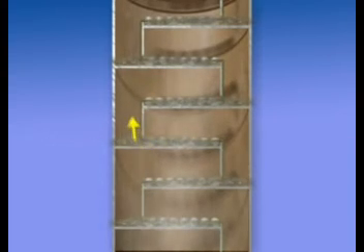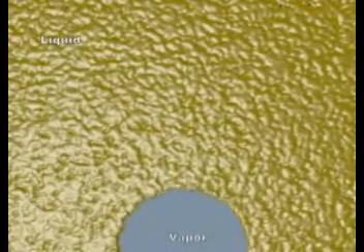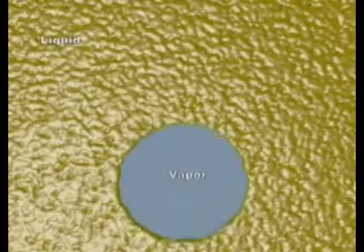Vapors will find the way of least resistance and will move up through the downcomer area instead of through the bubble caps. No interaction between the liquid and the vapors will be established, and the distillation process will be seriously compromised. The interaction between the liquid and the vapors is vital to proper distillation.